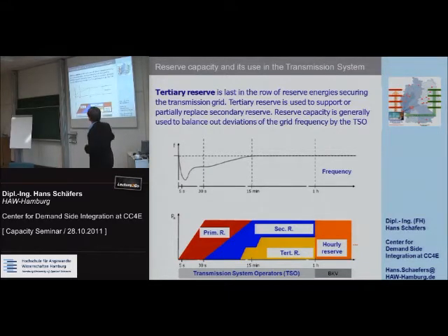That's why it's mentioned above, but I just want to hint at the situation that overall in Europe, if we see a frequency deviation, primary reserve capacity in the large generation sites actually kicks in and tries to reestablish the set point of the frequency. And it's a burden sharing, right? We see a deviation in the frequency in the European grid, and all the big power plants kick in. And then after at least 30 seconds, they're freed again, and secondary reserve capacity power plants are started.